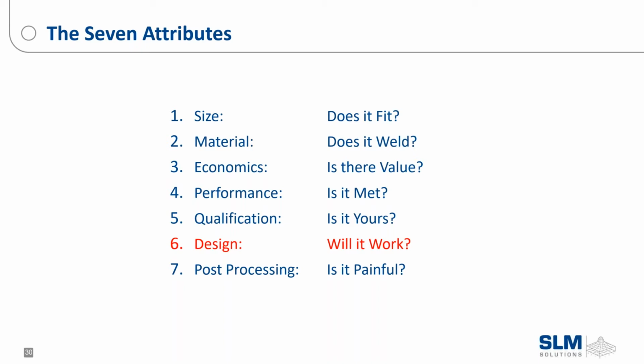If it requires the part to be forged, the part will need to be forged. If the callout requires the part to meet an AMS spec, and the AMS spec refers to a part made by casting, we cannot use additive.